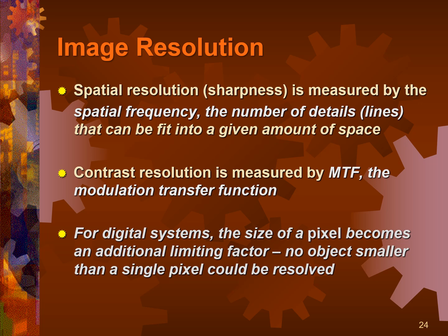Contrast resolution is measured by modulation transfer function, which is how well do we transfer frequencies? What? Well, let's go back to think about frequency processing. Remember we said high frequency objects were bright pixel, dark pixel, bright pixel, dark pixel. Well, that's a line pair. Okay, so that's a high frequency line pair pattern.